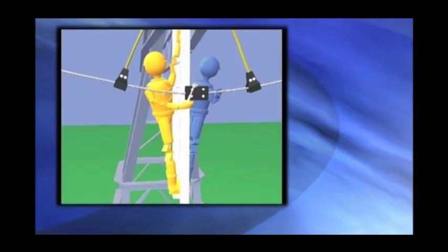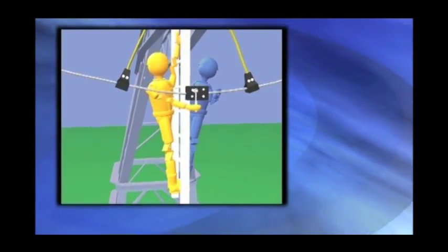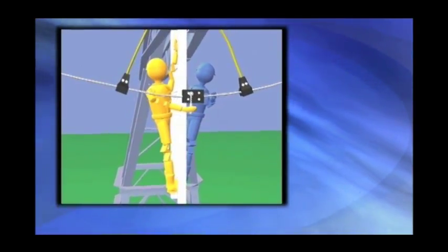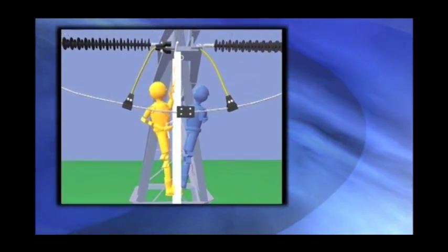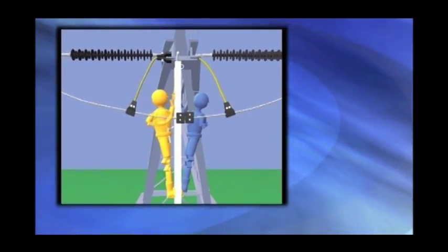The basic concept was to establish an equipotential zone for the workers. However, several errors compounded to create a hazardous situation. The temporary personal grounding cables were not installed properly on the painted structure. The paint was not removed carefully to ensure good electrical contact between the cable clamp and the structure. This raises an important point. Do not rely on mechanical contact to carry current. Mechanical contact often results in poor electrical contact since the contact resistance can be high unless proper precautions are followed, and in this case, cleaning off the paint.